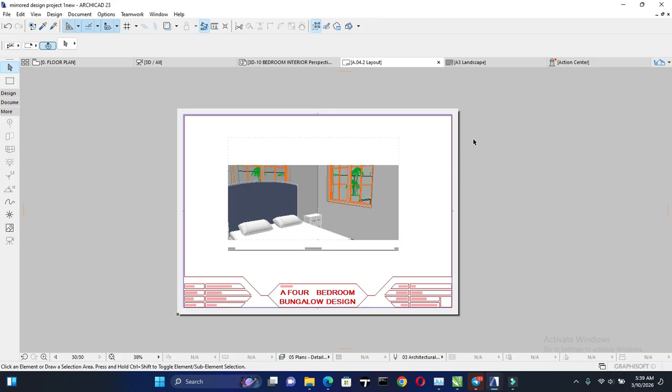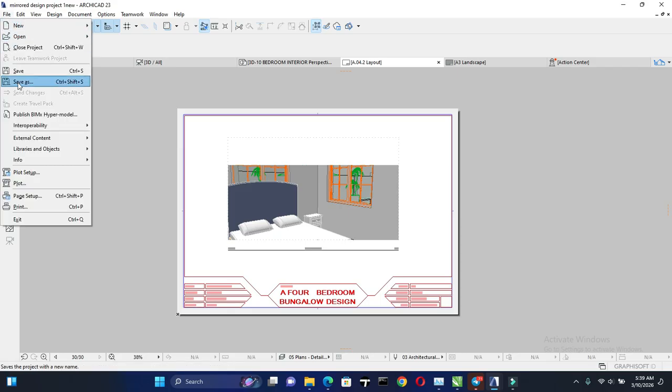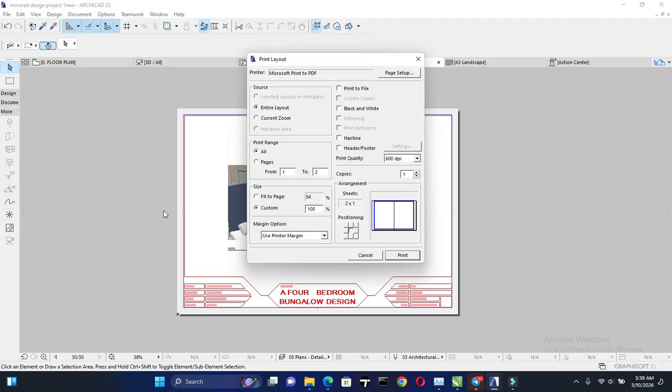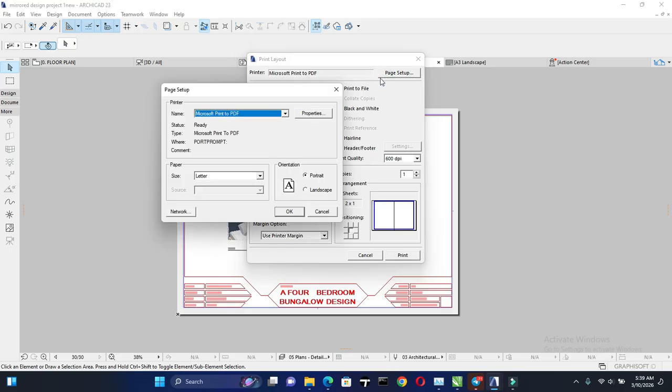But if you want to change your setup and print it formally, you select from your printers. But make sure that your sheet matches the sheet you use in your design. So, A3 landscape. Have you noticed how everything sits properly now? Alright, so with that done, select print range, all pages, but it's just one page that's added, and the header and footer. So all these things you just plug in, and know what you want.